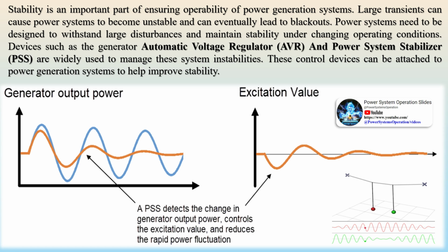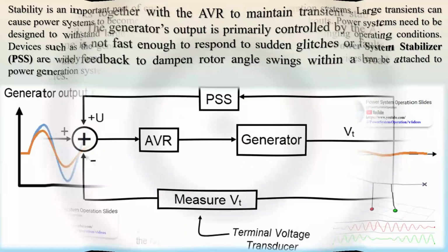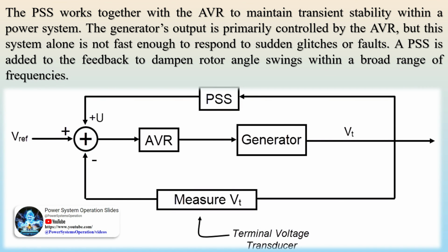Power system stability is defined as the ability of an electric power system, for a given initial operating condition, to regain a state of operating equilibrium after being subjected to a physical disturbance. Oscillatory stability, a subcategory of small signal stability (SSS), is defined as the ability of a power system to maintain synchronous operation under small disturbances. These oscillations typically occur at frequencies between 0.2 to 3 Hz with insufficient damping.